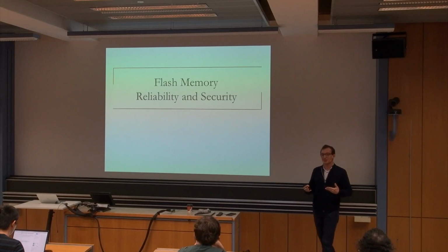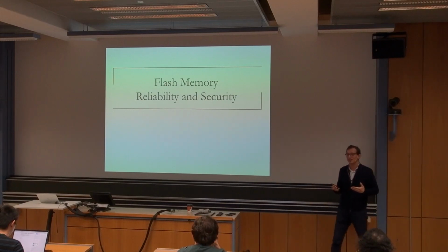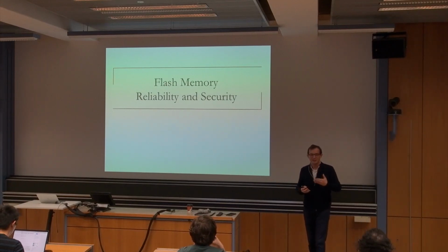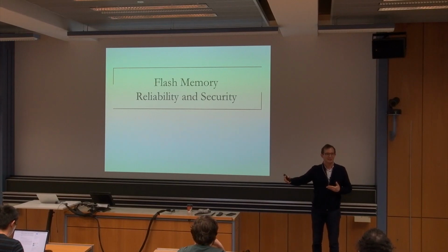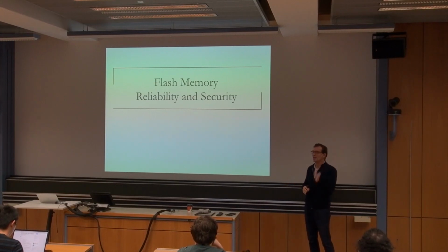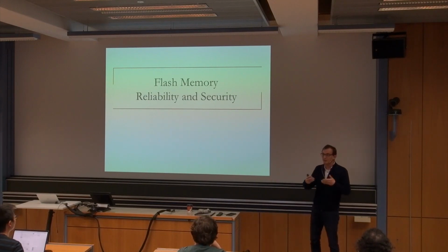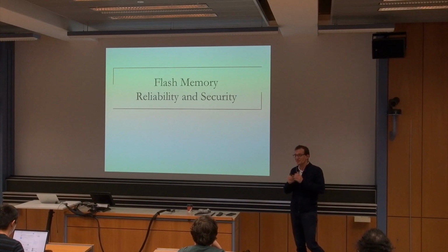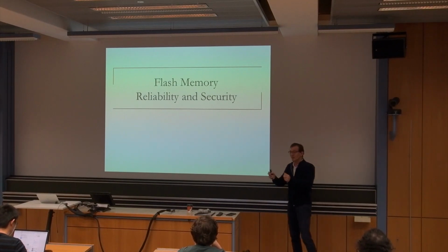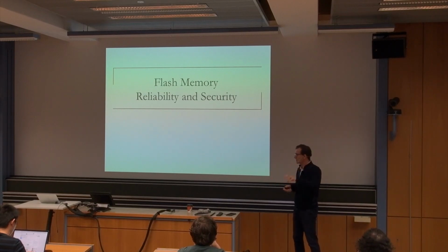So one of the big jobs of the flash translation layer is to keep track of what block exists where, because it does a lot of these remapping. You have a logical block address that gets remapped to physical locations, because whenever you modify, you actually cannot directly modify, you need to remap it. That's the idea. Now, okay, you remap this page from this block to this other block.